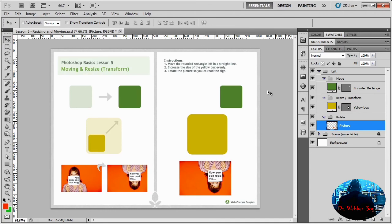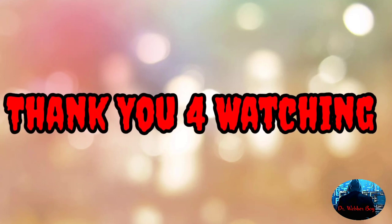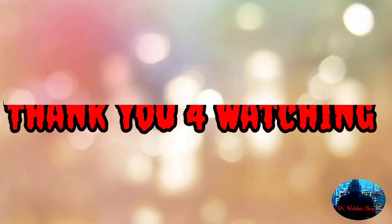So that has been moving, and we've looked at how you use the Shift key to hold it down, and that means that when you move something, it moves in the same plane rather than it being a bit random. Same thing goes for resizing. If you want to resize it and keep the aspect ratio perfect, again, hold down Shift. And then lastly, we rotated an image, and we saw that holding down Shift helped us get it exactly 180 degrees so that we can read the sign. So that's everything for moving and resizing. Next, we're going to be looking at zooming and panning so that you can really get into your design and look at things in a lot more detail and get everything pixel perfect.